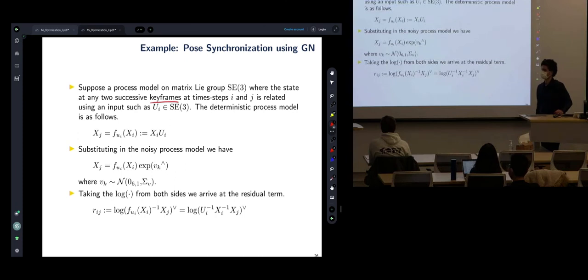How do you determine the keyframe? Is it maybe the number of unique features between subsequent frames? This is a question for future lectures, but how do you define the keyframe? That's an existential problem. You can set a threshold on time. You don't want to go too far. You can set a threshold on the overlap between detected features you're tracking.